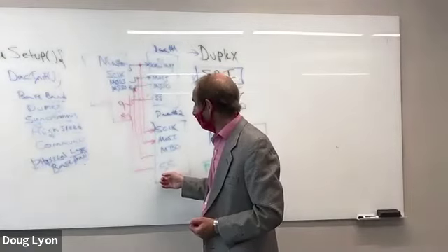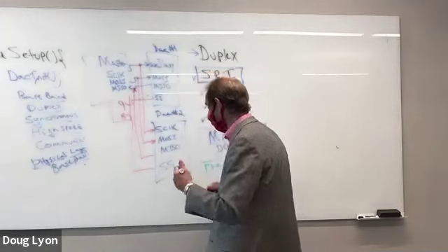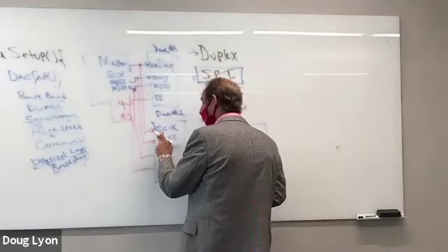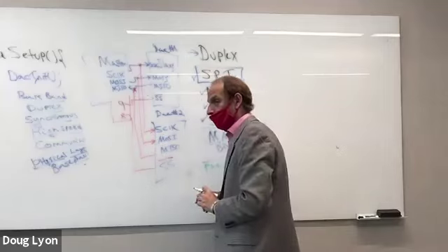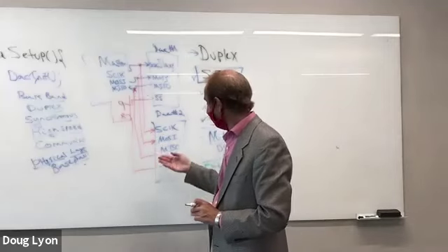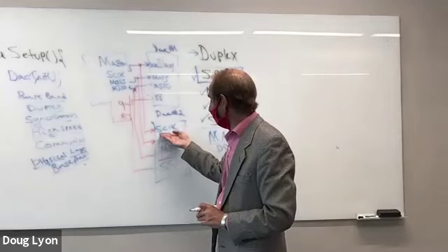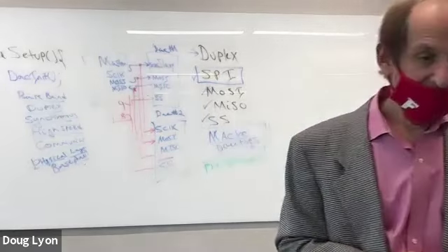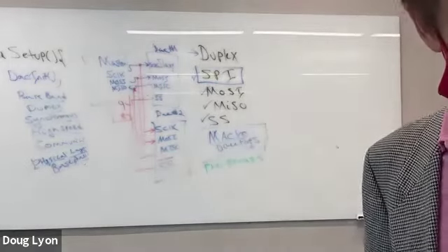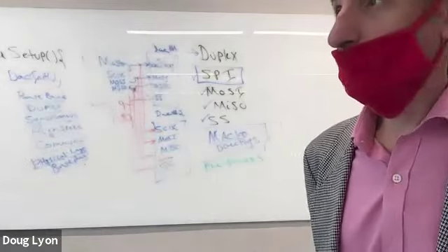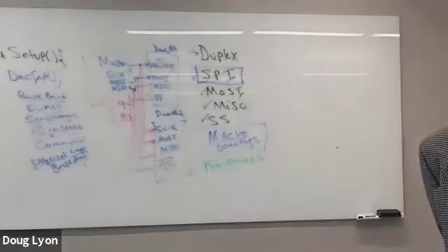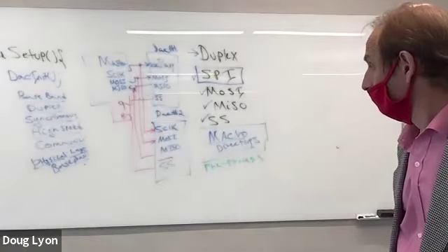And when they're not selected, they have to drive their outputs into a high impedance state. And they have to ignore the inputs. Have to ignore them, except for maybe the serial clock. And the reason is, you know, if you don't, then what's going to happen is you're going to start outputting spurious data on one of the DACs. And then it isn't going to work right.